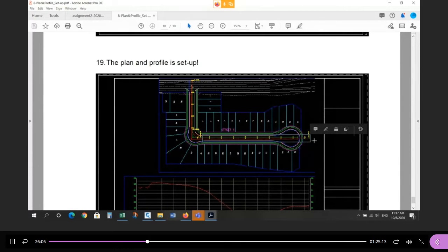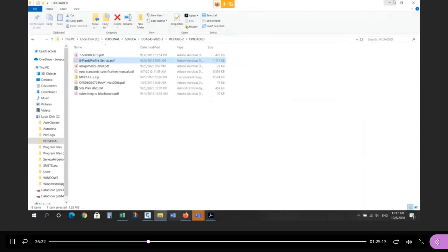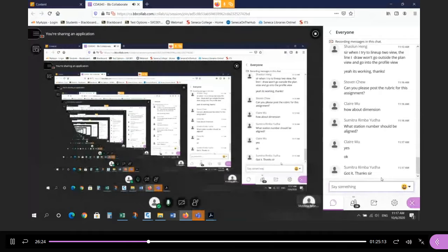So I can't answer your question; it depends on which street you have. Once you create the view, rotate the view, and then whichever part of the center line is horizontal, any station on that horizontal leg can be used. If you have more than one, as in my example, any one that's on that horizontal piece.